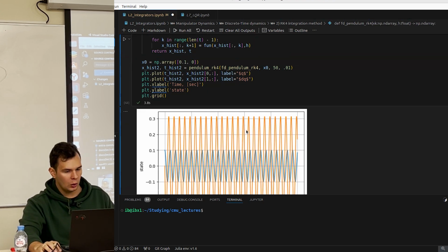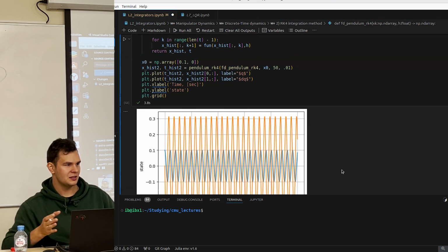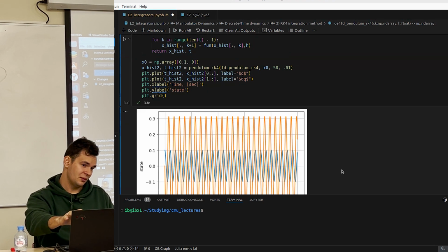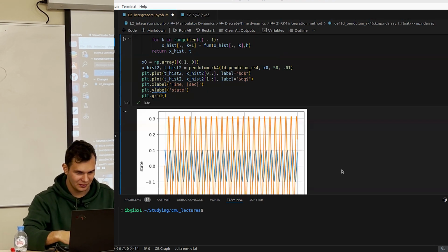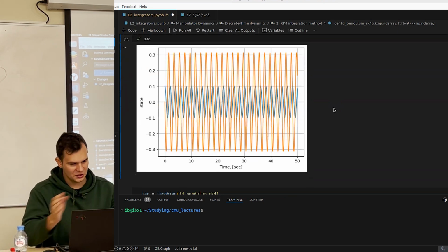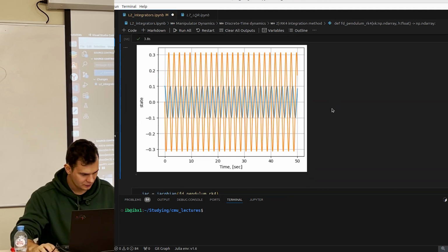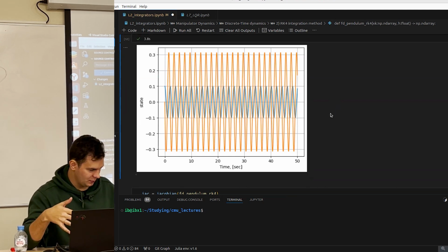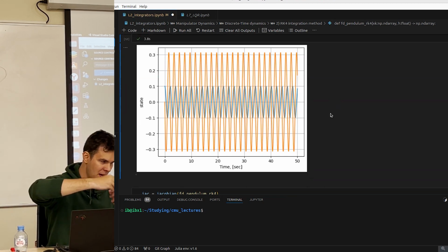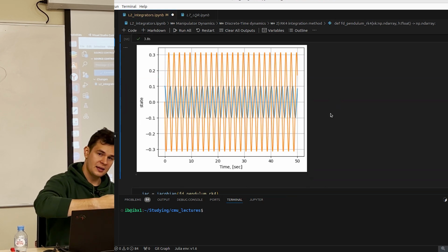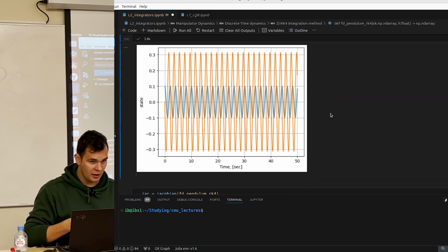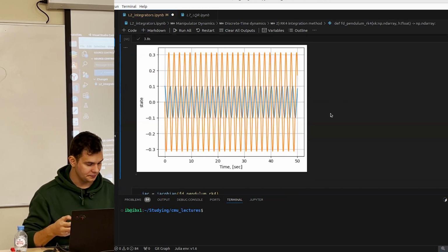But it's always precise, and it is industry level. And you can use it. It's very great. And by the way, right now we're going to use it, I believe. Okay, just let me finish with integrators, and then we go back to the mass spring damper. So it is explicit. Why is it explicit? Because it uses just the previous state, and it makes a prediction of what will be the second step. Forward Euler uses linear approximation, and the Runge-Kutta uses a cubic approximation.